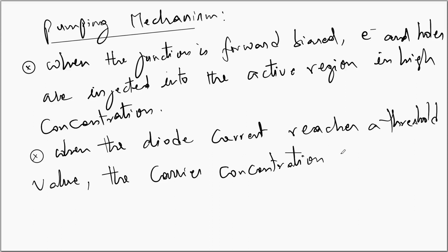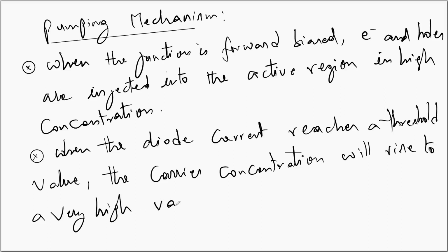The electrons injected from the N-type gallium aluminum arsenide layer into the P-type gallium arsenide layer confront an energy barrier at the junction where P-type gallium arsenide and P-type gallium aluminum arsenide meet, and are reflected back into the active region. Similarly, the holes are reflected by the potential barrier provided by the higher band gap N-type gallium aluminum arsenide layer. Thus, the layers in the heterojunction structure confine the charge carriers to the gallium arsenide layer.